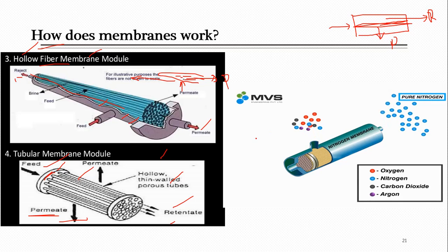So this is the permeate, and the other which can't pass through this membrane will leave as a retentate. Here in this illustration you can see that some gas mixture is entering the membrane module. This is similar to the system which you have seen here, the tubular membrane module. Some of the components pass through these tubes and leave; they are impurities.